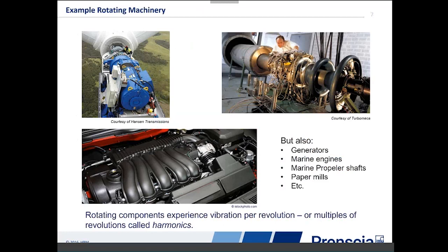energy, of vibrational energy at every revolution. Other phenomena appear twice per revolution. For instance, if we take your car's engine, say it's a four-stroke, 4 cylinders thermal engine, you've got 2 sets of explosions per revolution of the crankshaft.